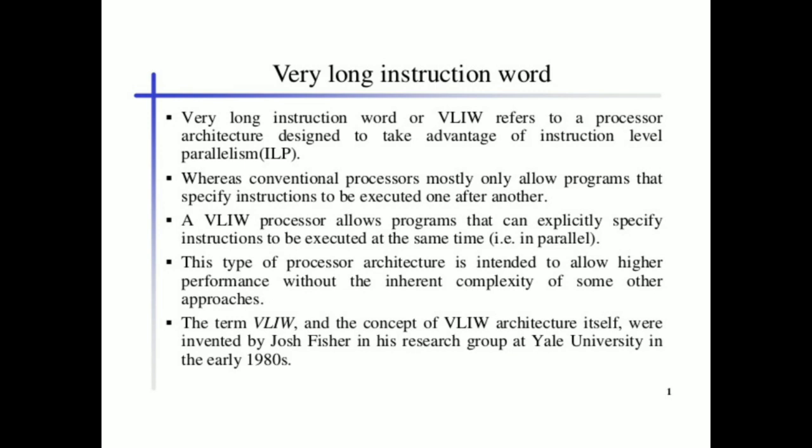In VLIW processor, the compiler is responsible for static scheduling of instructions, that is, the compiler finds out which operations can be executed in parallel in the program. The compiler groups together these operations in a single instruction, which is the very large instruction word.